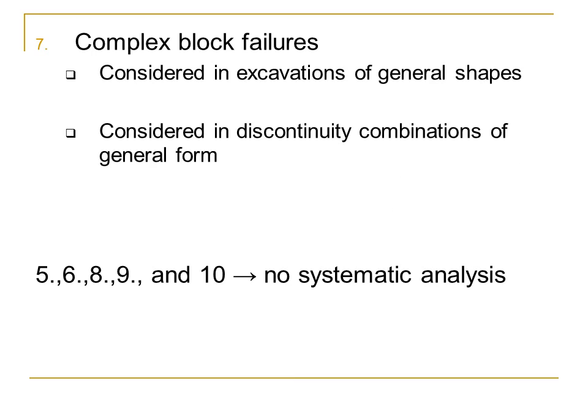There are a number of complex blocks that I want to take a look at next. These need to be considered in excavations of general shapes, so they don't necessarily have to be a uniform profile, and that will often introduce the potential for complex blocks. Another case would be a circular quarry, so that you're going to have different orientations to the cut slope, and that will introduce the potential for complex blocks.